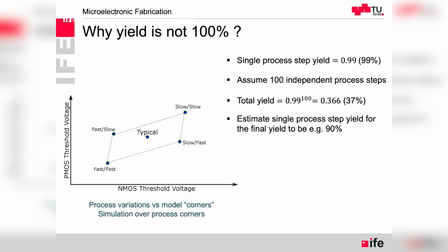Of course, not all the processes are related to MOSFET transistors. There are metallizations. And also another tool is Monte Carlo simulation, which helps estimating what will be the final yield. So there is a lot of contribution to the final yield from the foundry, but also from how thorough the design is being made.